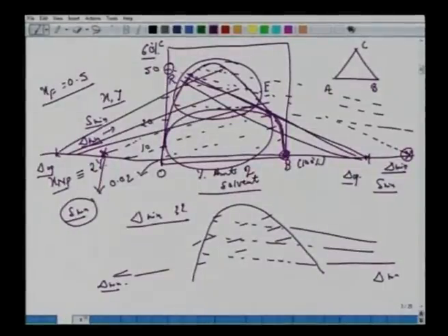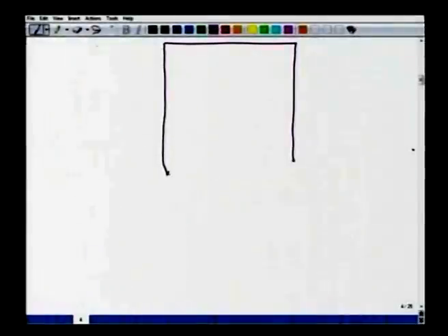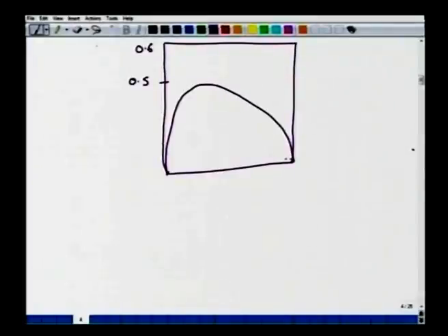So what we do here again, to find this minimum amount of solvent, let's redraw this equilibrium phase diagram. Here we have 0.6 or 60%, and feed is say 0.5, 50% here, and the phase diagram looks something like this. We have the raffinate, which is 2%, so this is 0.5, 0.4, 0.3, 0.2, 0.1, a very small concentration here, let's say 0.02.